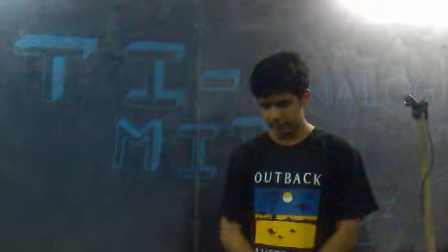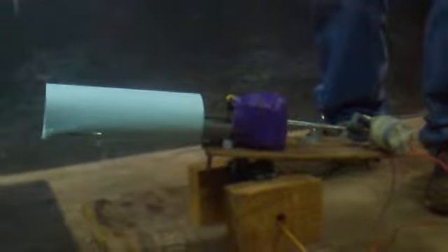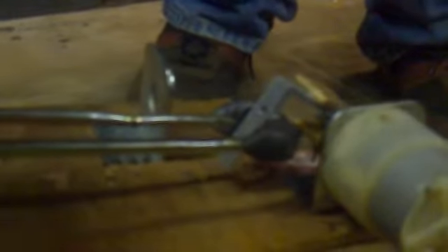Good evening, I am Siddharth Dave, student of 6th semester mechanical engineering. I will be explaining the mechanism of the cannon. What we decided to use was a simple yet effective mechanism that guarantees both accuracy as well as reliability. The cannon is powered using two springs which are supported by two steel rods mounted coaxially with the springs. To trigger the mechanism of the cannon, a DC motor has been used which is mounted over here, and to rotate the cannon about the vertical axis, a servo motor has been mounted over here. The electronic aspects of this project will now be explained by Gokul Nayak.